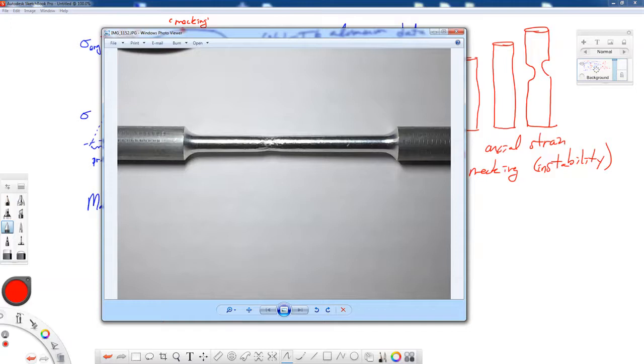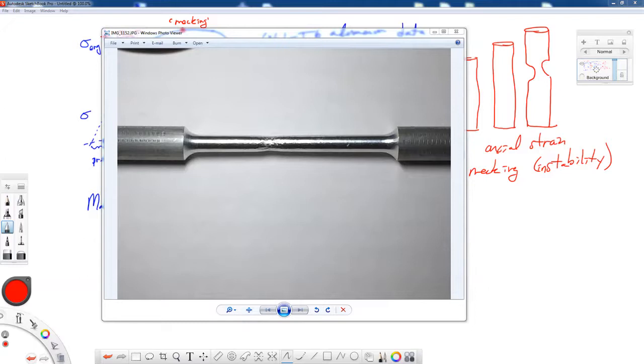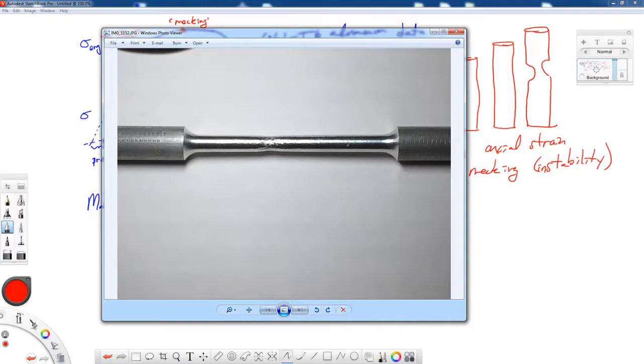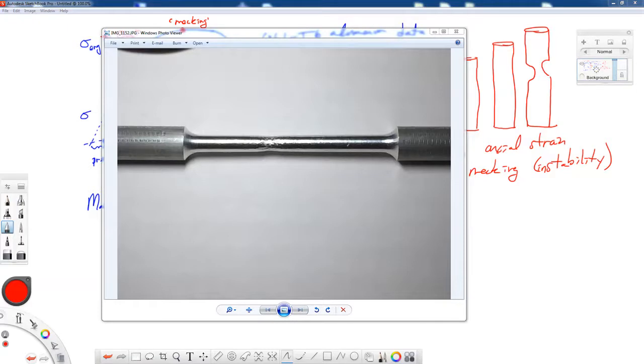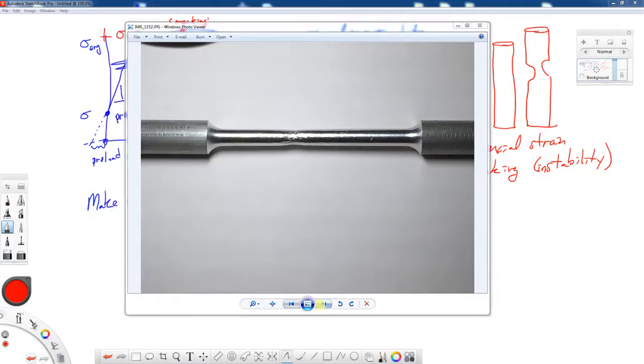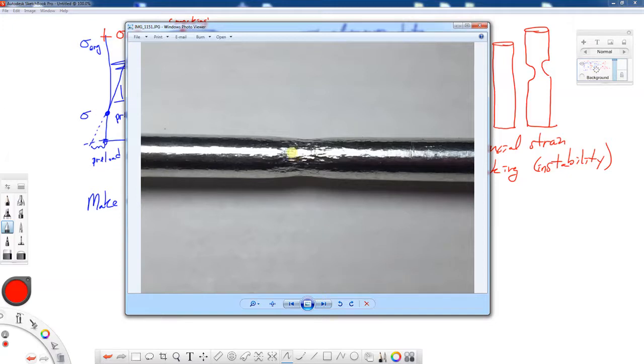And so here's the specimen grips that I have here. You see the indentation where that was biting in. And here's the gauge section. Here's my radius of curvature. And you can kind of see it in this picture where I stopped this test at necking. I didn't break this specimen. Let's see if I have another picture where I've zoomed in on it. There we go. And you see the surface is kind of mottled. It's beginning the failure process.